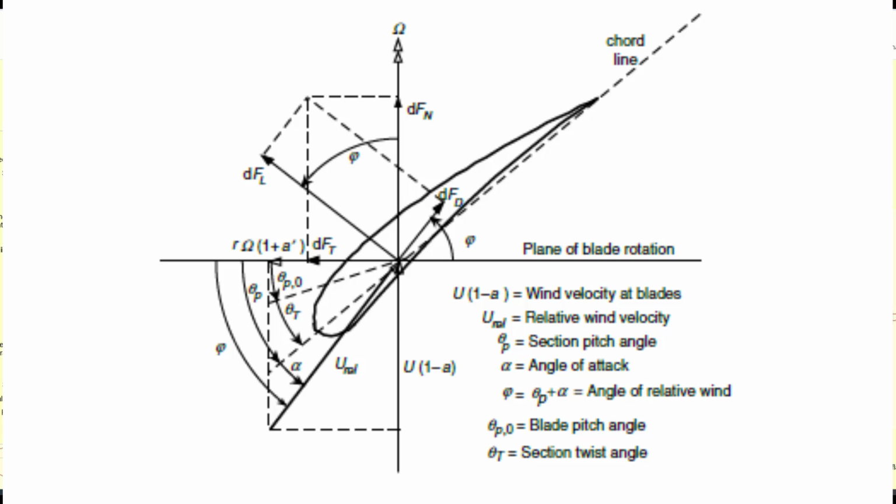So you see here, we'll just discuss basically two steps. There are other steps, but we are looking at two steps that are usually used for generating the geometry and optimizing the wind turbine blade geometry and aerodynamics. So one of the approaches, method one, is where you select an airfoil. You already know the airfoil you want to use, and you use that airfoil. You use the lift as well as the angle of attack in order to generate the angle of relative wind speed as well as the twists. You'll be able to generate such parameters.